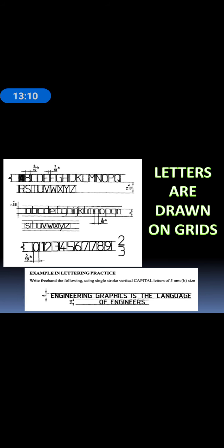In this slide we discuss that in the starting we take a height. For example, we can take a height of 14 mm for a letter. Then the width is set according to 7:5. In the starting we can draw a grid in the drawing sheet, and then divide it into 7 boxes in the vertical direction and 5 boxes in the horizontal direction.